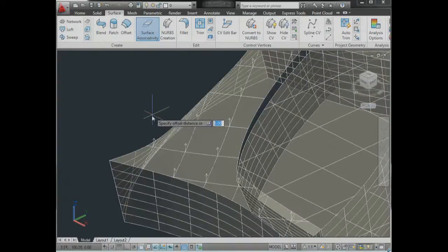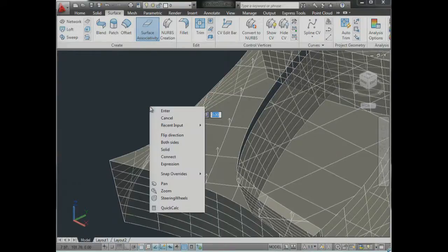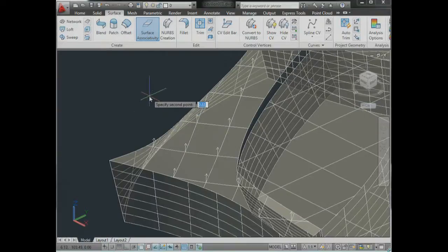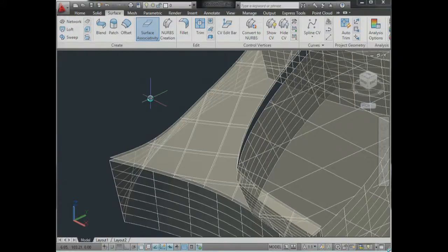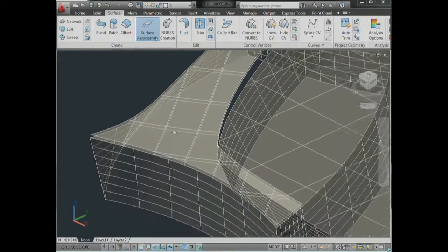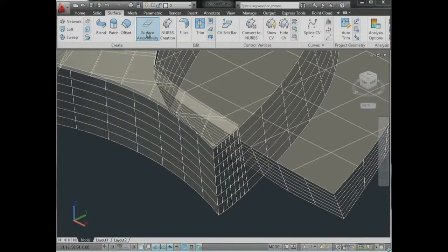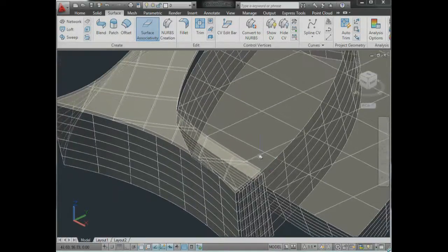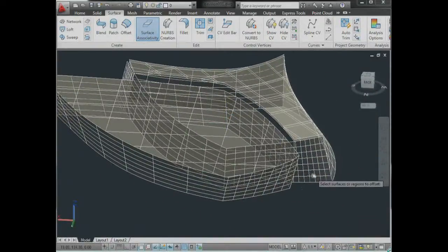Another thing I want to do is make an offset, because I need depth, right? I need to have some thickness there, so then we as architects, in this case, can understand what we're doing. So what I'm going to do now is just, again, create a little offset of the surface, for example, in this case, 40 centimeters, right? And we have what we call direct manipulation, which means since this is understood as an offset surface, it has controls that let us just go back and forth and keep changing things at any time of the process. Now I'm going to do another offset of this slab, again, 40 centimeters, and I'm basically going to repeat the same operation at the back.